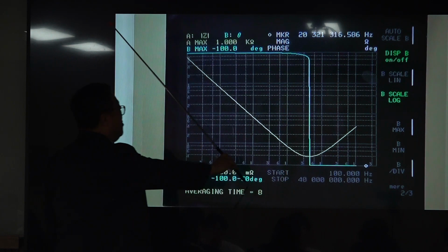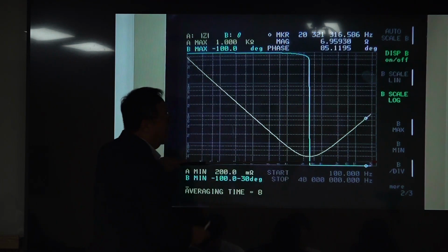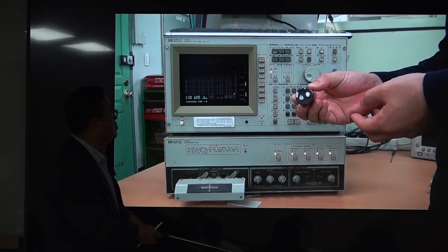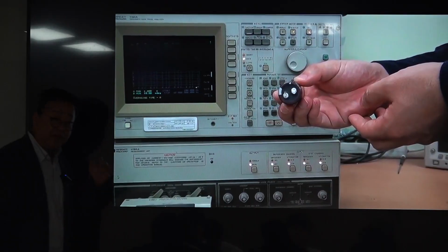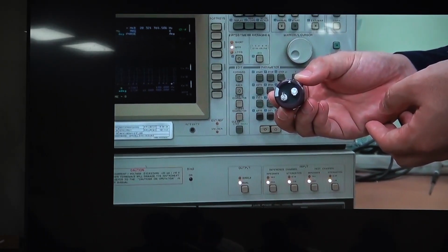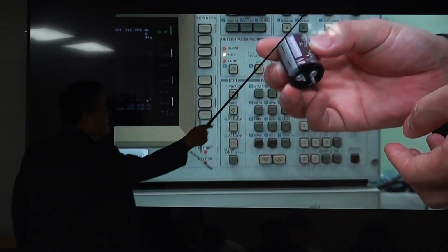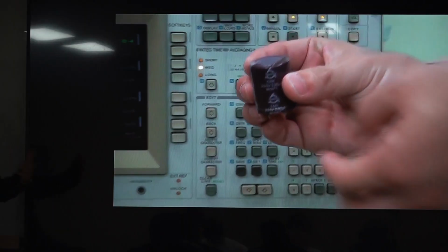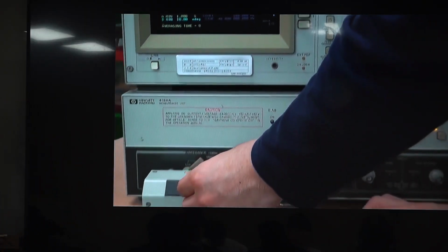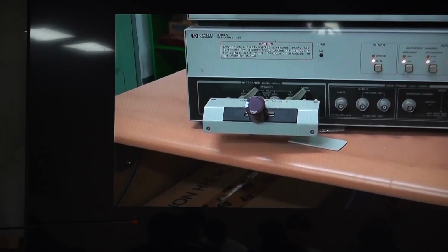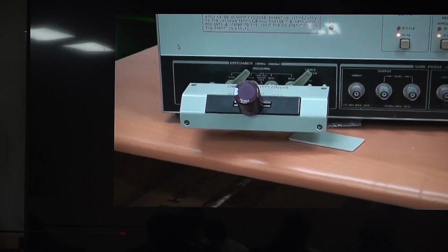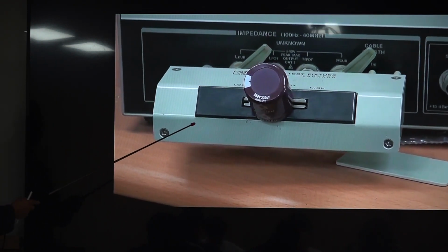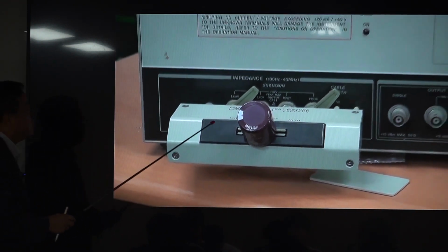Right? So this is the capacitive curve, the inductive curve, and this value is ESR. Okay? This is a good one, right? So if you have, oh, this is a bad one. This is the cheaper, not bad one, cheaper one. This is the electrolytic capacitor. Then the curve may look like this because the Q value is very small. Q value is inversely proportional to the ESR. Okay? High frequency capacitance, high voltage capacitance.